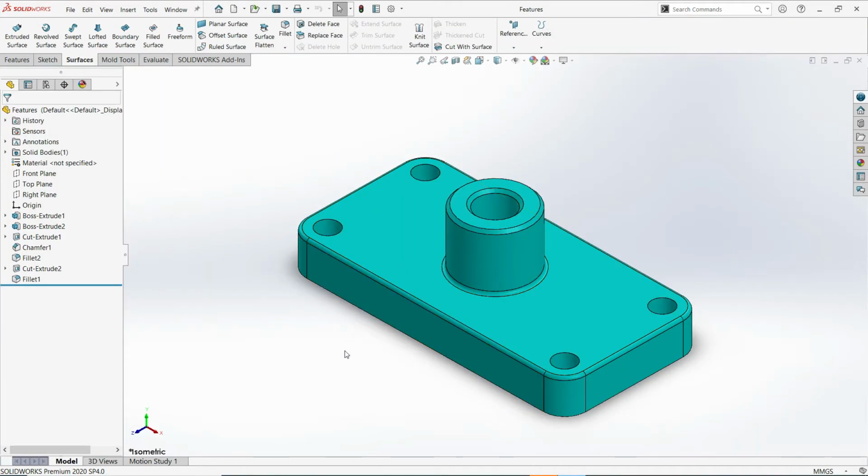When we say sketch features, they are based upon a 2D sketch, which then later transforms into a solid by means of extrusion, rotation, lofting, and/or sweeping. Applied features are created directly on solid models, like fillets and jumpers, which don't need a 2D sketch profile.